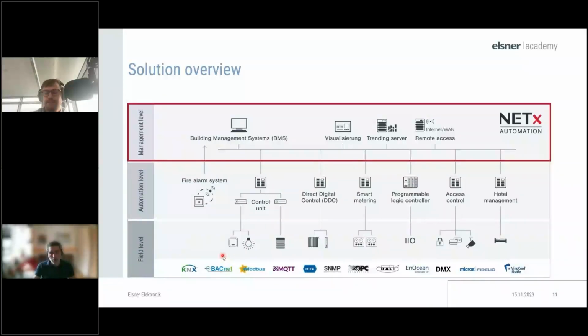You may also know Modbus. Modbus is more coming from the industrial automation domain, but it's also used here in building automation. And for example, smart meters are using this protocol for providing an interface to the energy consumption, for instance, or also PV stations, PV inverters are sometimes using Modbus to communicate with them.